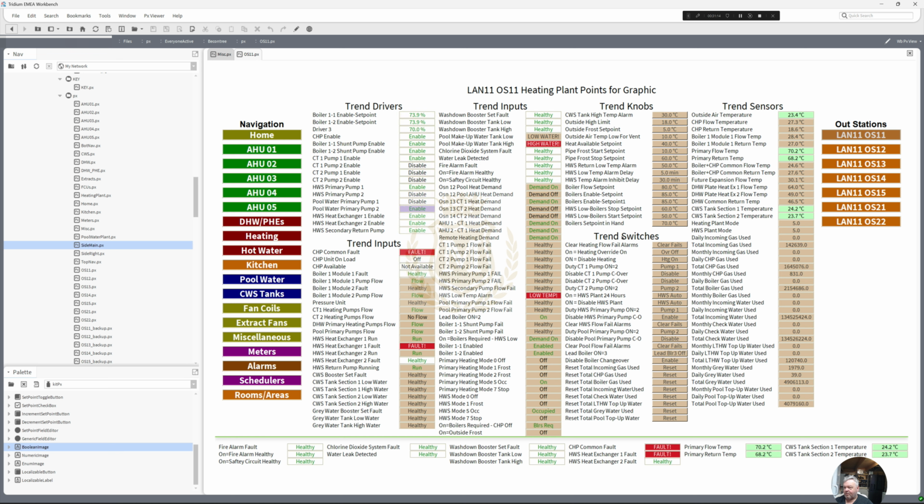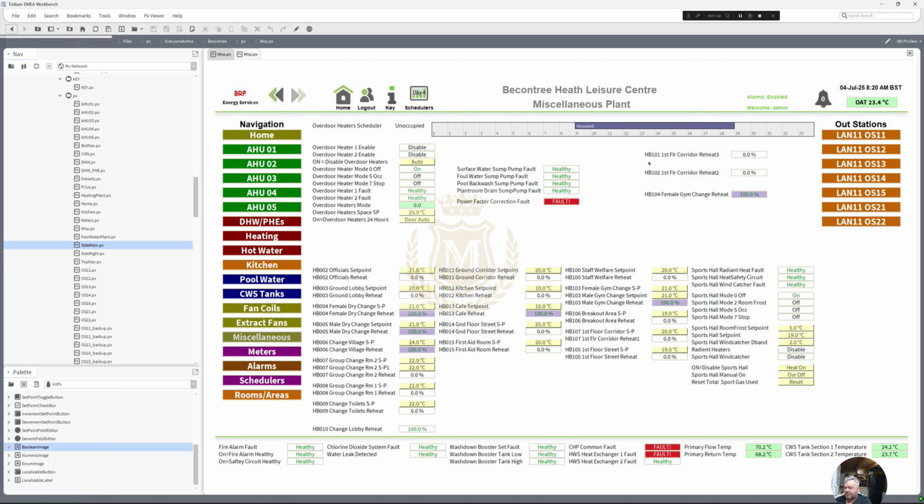So I may have to go into the set software and have a look what the control variables are for these heater batteries that I can't find, because there's no 101 in any of them, no 102 and no 104, unless they are controlled from another set point.